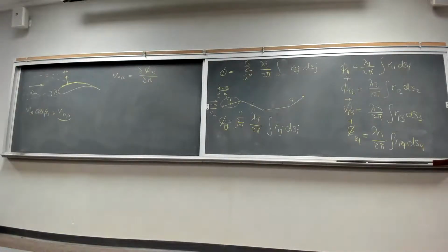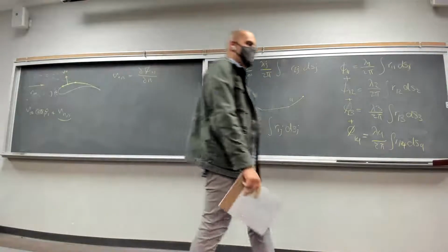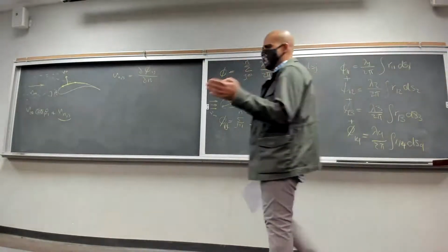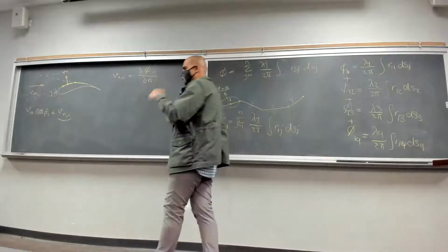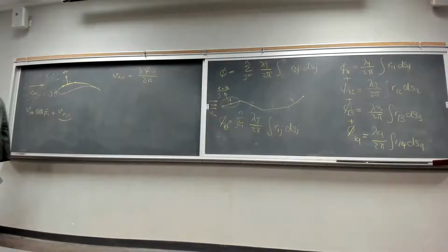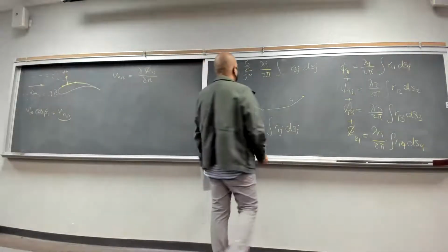That's it. That was the idea of the velocity potential. If you have the velocity potential, to find the velocity in any direction, you have to take the derivative of the velocity potential with respect to that direction, right? For a stream function, it was a little different, right? For velocity potential, it was a little more straightforward. Okay, so let's take that derivative then.